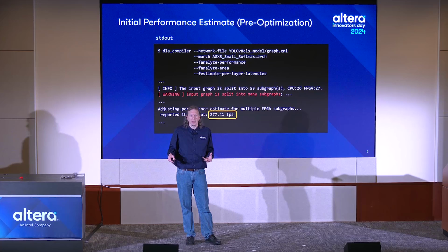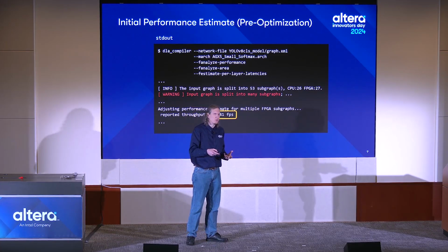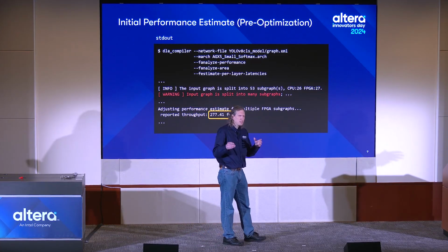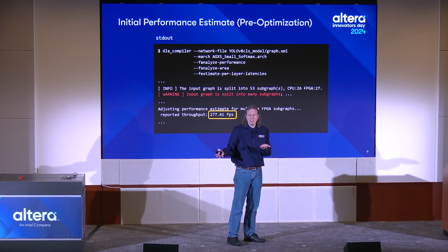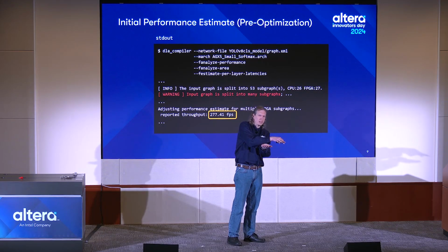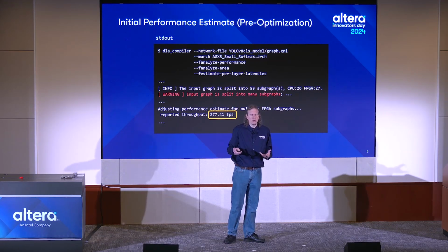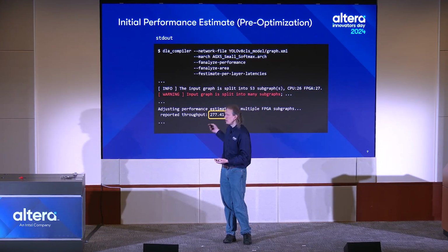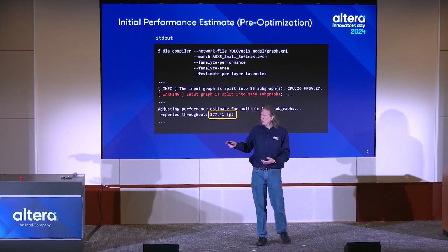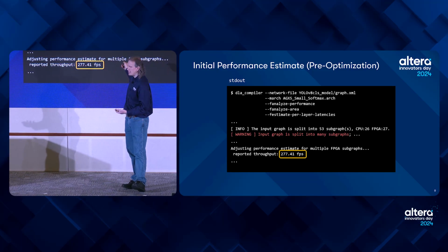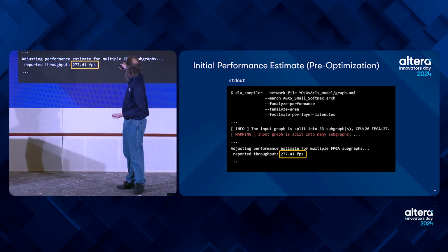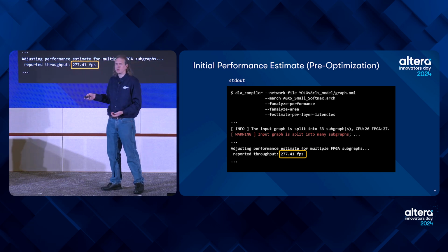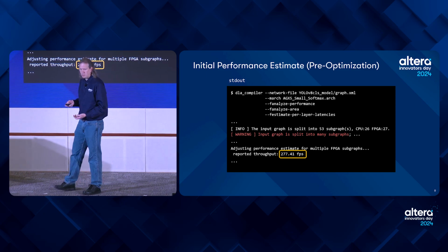The example runtime that is included with the AI Suite example designs will seamlessly stitch between the FPGA and a PCIe attached host, or between the FPGA fabric and an SoC attached host in order to execute inference for this graph. So even though we see this warning, this graph is perfectly functional with 53 subgraphs, 26 of which will execute on an attached CPU.